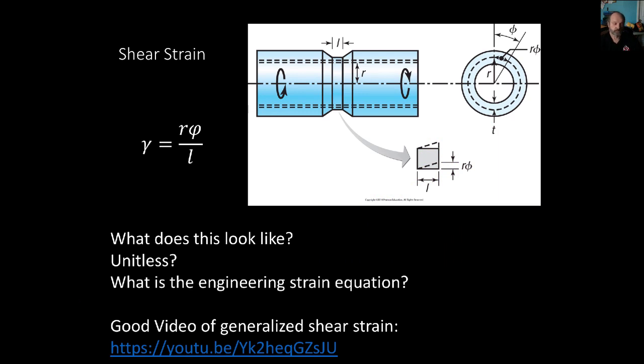All right. So that's the force that we apply to twisting it, right? Now we're going to see how far did we twist it, and we already mentioned that. That's the shear strain. So it's R theta over L. So R is the radius of the pipe.